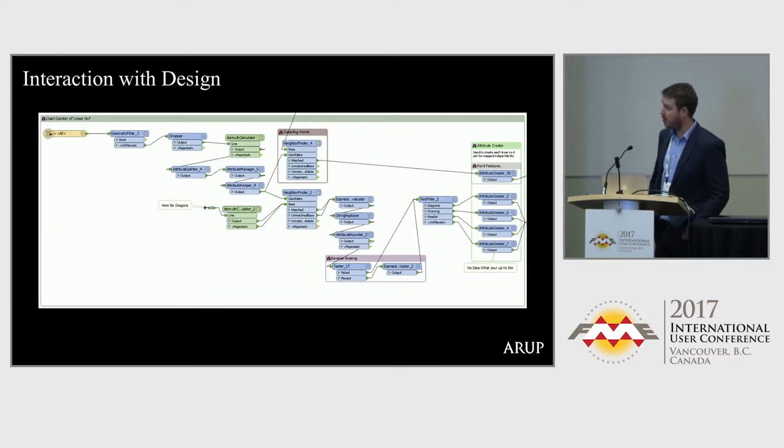Another cool thing that we did, we took into account the interaction with design. We had the centre lines from design, and also took the angle of the actual asset itself. We would calculate those against each other to determine whether it was a perpendicular or a parallel clash with the alignment, or if it was a node clash as well. The node clash was a bit easier because it's a point, it's in 2D, so if it's a manhole or something, it's got to come to the surface, we're going to hit it.